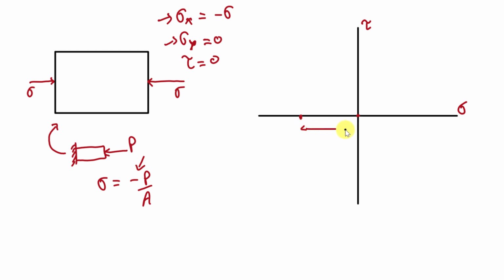And here this distance is sigma. Now we are going to mark this point where sigma y is equal to 0. So we know that at this point sigma is 0. Fine. So now we have these 2 points, and by using these 2 points we can draw the Mohr circle. So at this time the Mohr circle will be something like this.